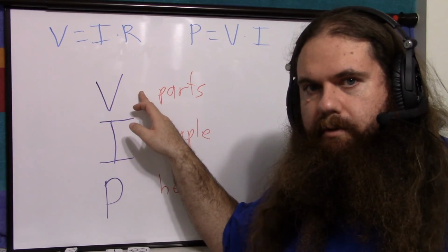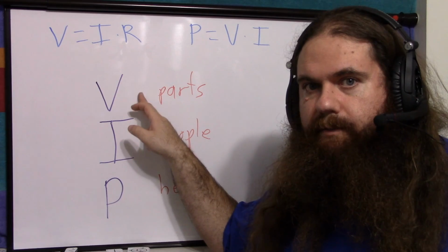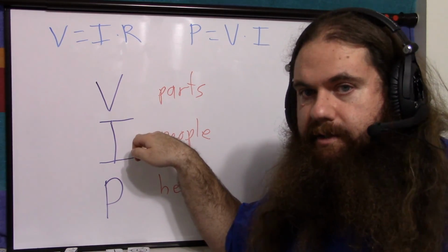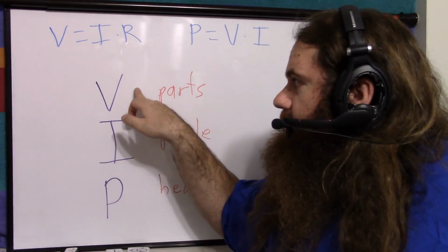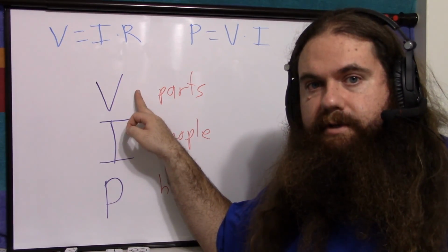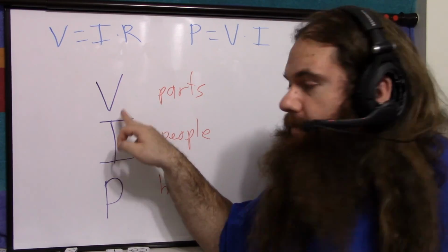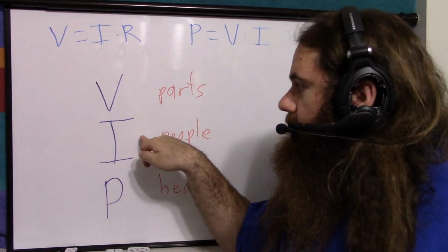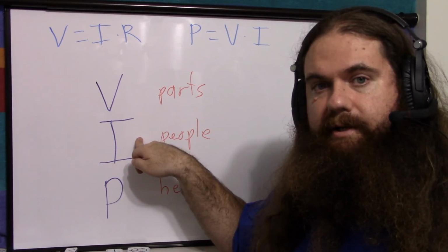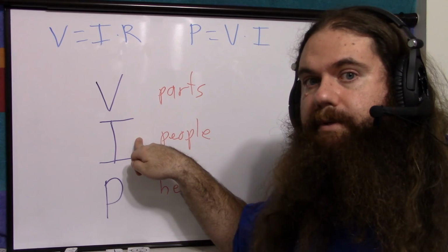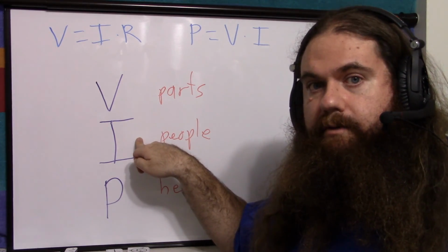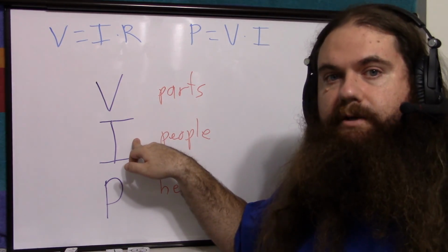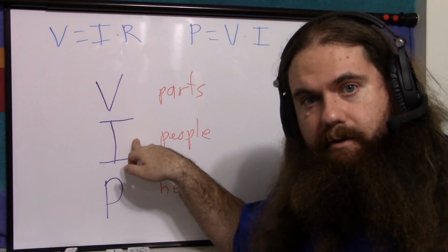The oscilloscope probe does not generate a voltage, so we don't have to worry about that. The oscilloscope probe has impedance, resistance, so we don't have to worry about this. If we just plug it into the port, the only voltage is created by the thing, and that should be safe. The only current is generated by the thing. We're not introducing current, and furthermore, if it's expecting an impedance, an oscilloscope will be plenty of impedance. So if we get a spike, we know we've got to be careful turning it down. If we get nothing, then we say, oh, we have way too much resistance. This thing is expecting a very low resistance.